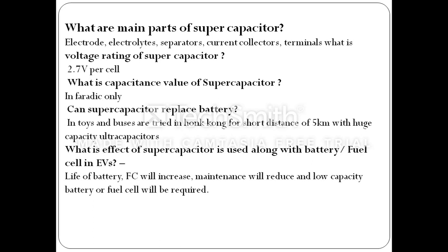Then what are the main parts of supercapacitor? They are electrode, electrolyte, separator, current collector, terminals. Then what is the voltage rating of supercapacitor? It is 2.7 volt per cell. Then what is the capacitance value of supercapacitor? It is in farads only.